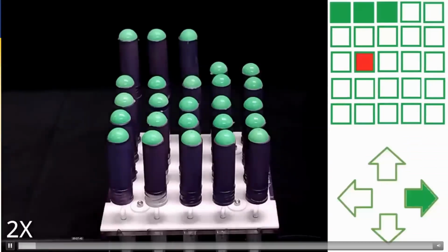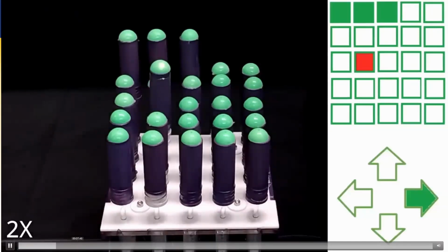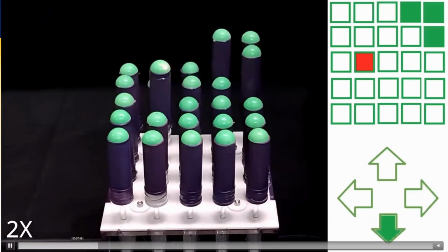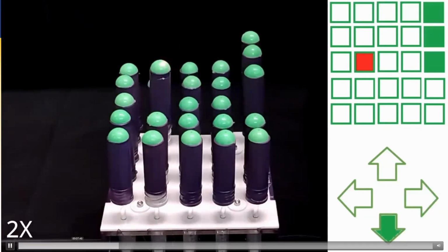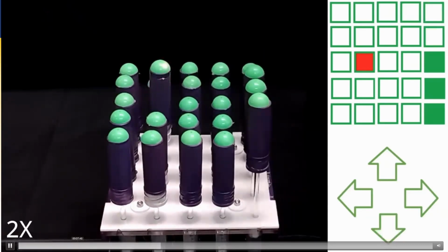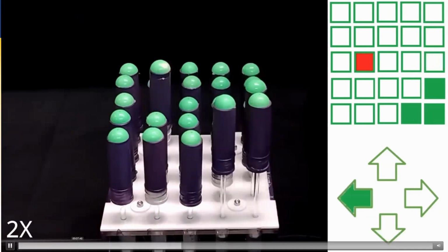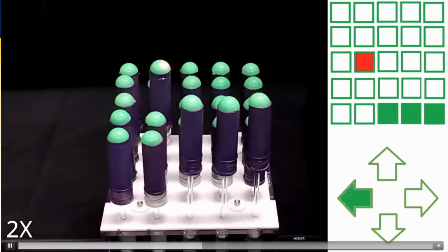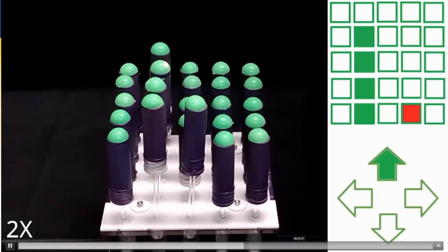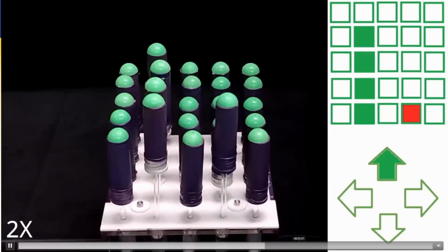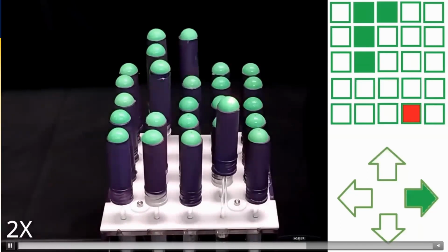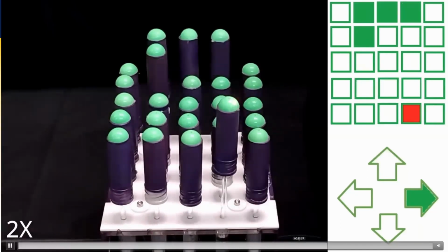We demonstrate the implementation of a fluidic matrix circuit for controlling a fluidically driven shape-changing display with 25 independent actuators arranged in a 5x5 matrix. The shape-changing display could render various shape patterns, including geometric patterns, numbers, letters, graphics, and incoming visual data. We demonstrate the shape-changing display rendering every frame of a snake game as the position of the snake was dynamically updated on a 5x5 grid. The two-dimensional array of actuators was refreshed by sequentially addressing each row within the matrix for a short period of time, as shown here.